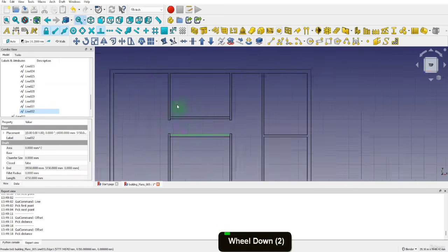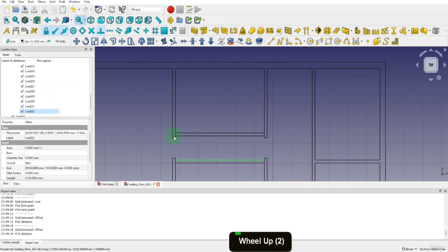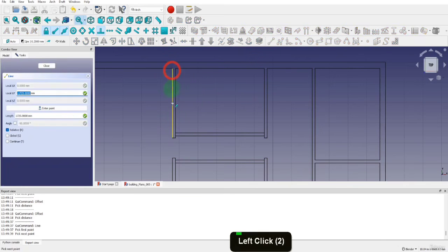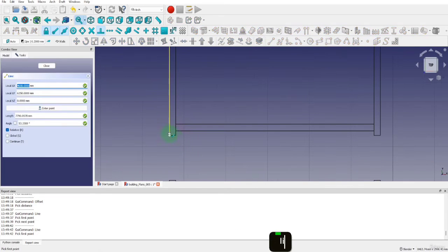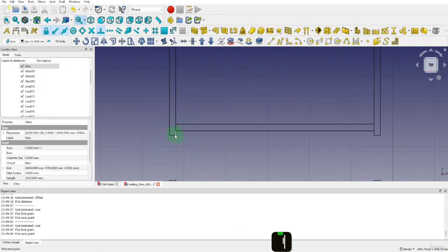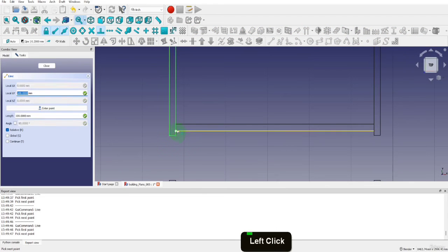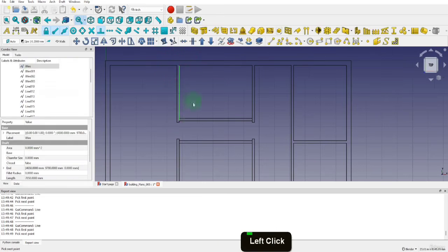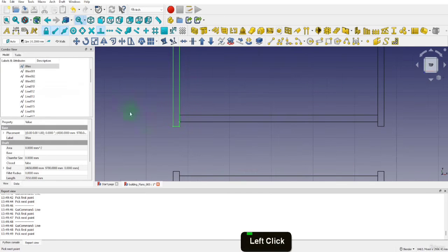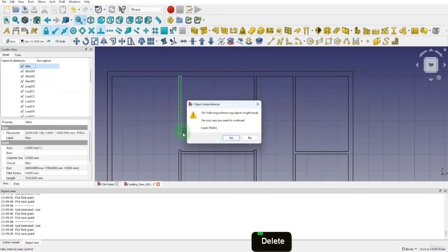We created these sections using the Wire tool, and the easiest way will be to draw lines over these objects, then delete them. So select the Line tool and start tracing over this shape. All the way around. Just skip crossing the joining wall. Finish this. We can then find the wire objects in the Walls folder. Press Delete and remove it.